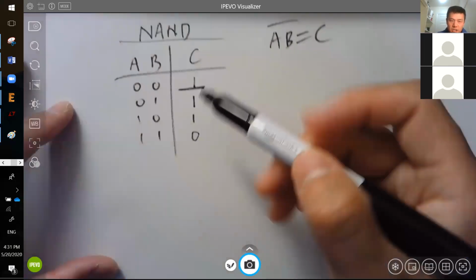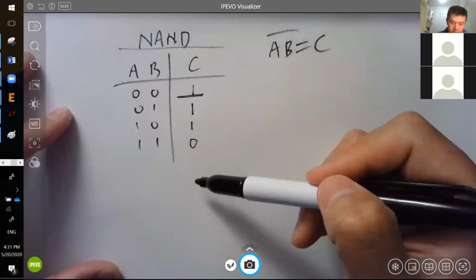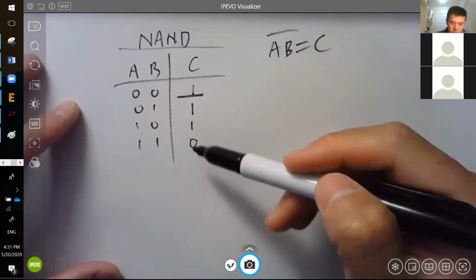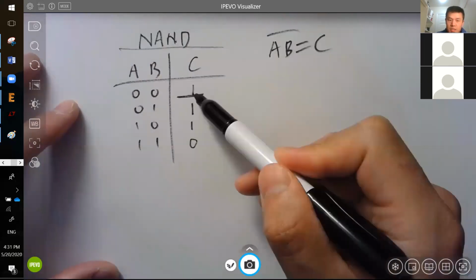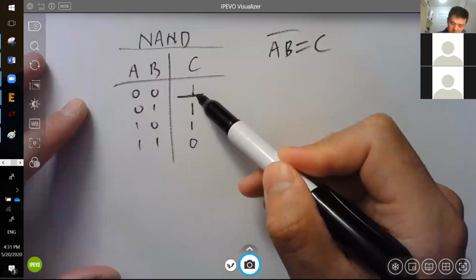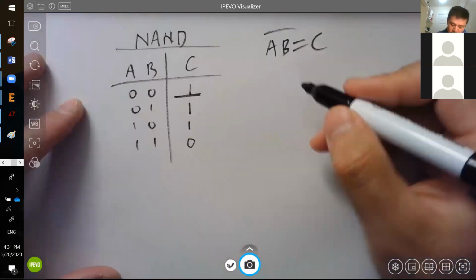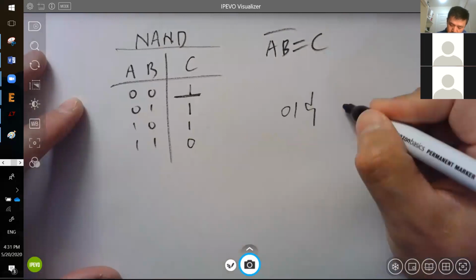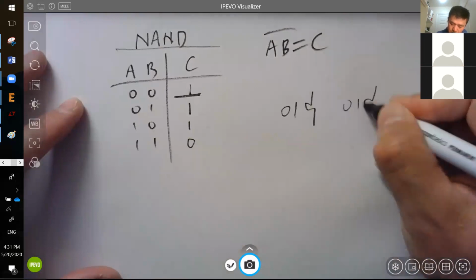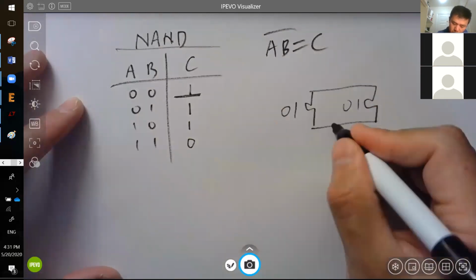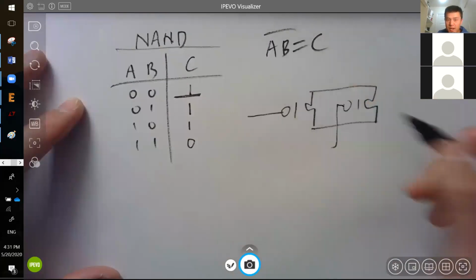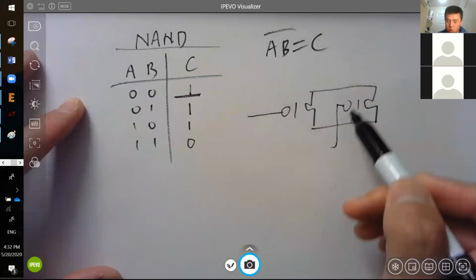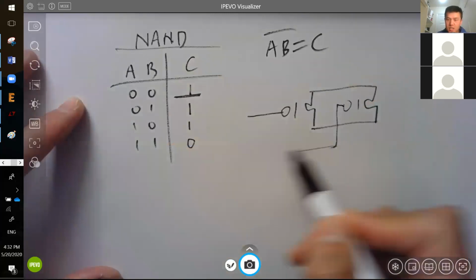So that's a NOR logic. Agree with that? Yes. So when the two inputs are zeros, you want to turn on the V out. If you have two PMOS on the top, you're asking why you need two PMOS? Because I have two inputs. Two PMOS will provide you two gates.